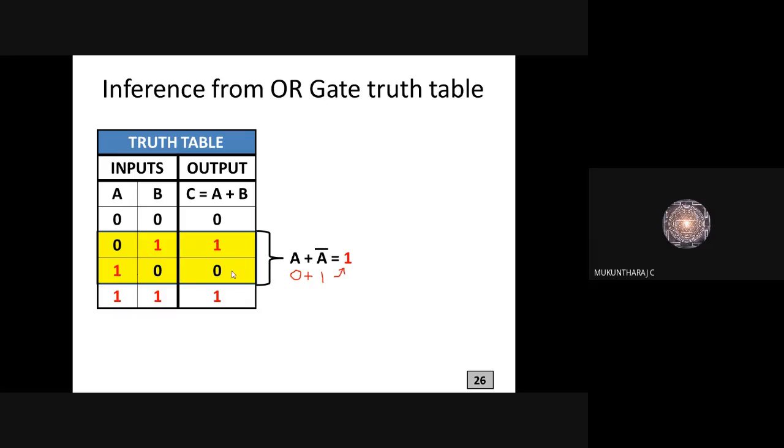Here actually this may be 1, because this is an OR gate. An OR gate definitely produces logic 1 if one of the inputs is logic 1. So here, this is not 0, it should be 1. Now input A has logic 1, but B has 0, the complement of input A. So 1 OR with 0 definitely produces logic 1.